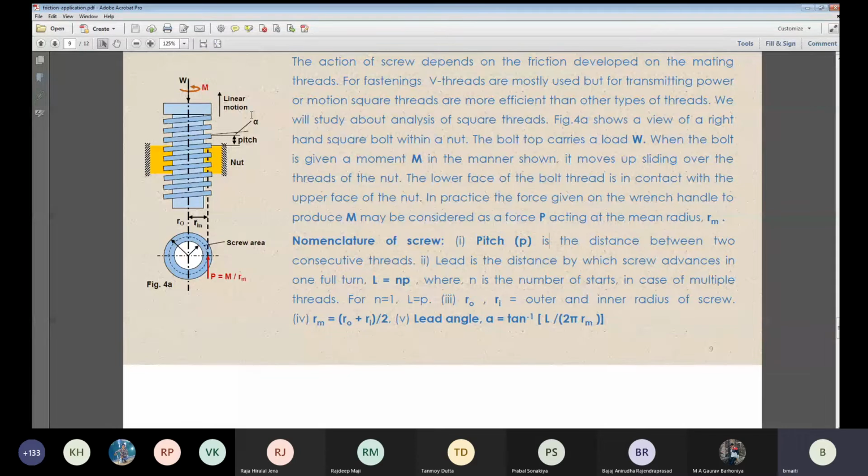Now, the lead L, that is called lead. So L is equal to N multiplied by P. N, as I told you, is the number of threads wound over a single shaft, multiplied by the pitch of each thread. All are similar types of threads. So that is NP. If there is only one thread, N equal to 1, then L is equal to P. There is no difference between L and P. That is the situation. So that is the reason the lead angle becomes...